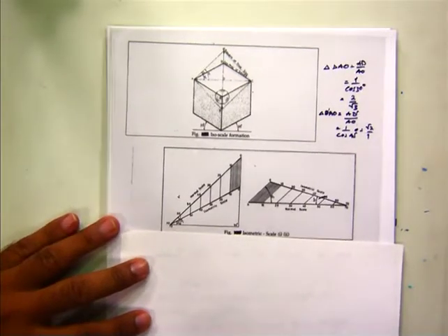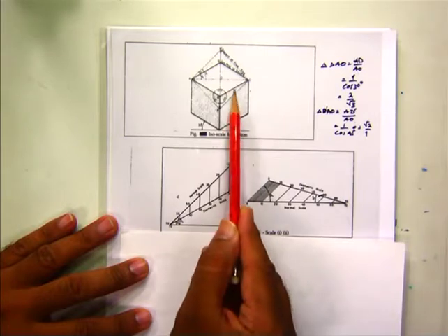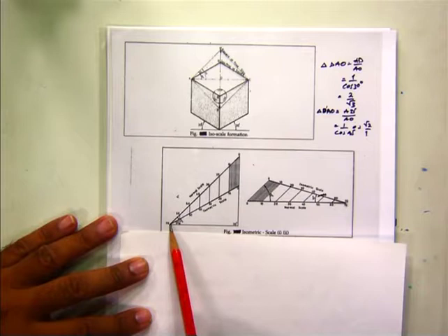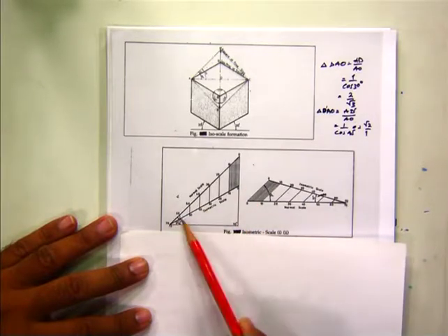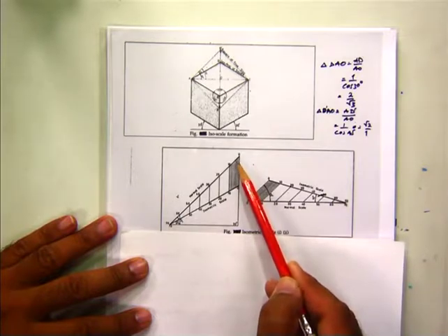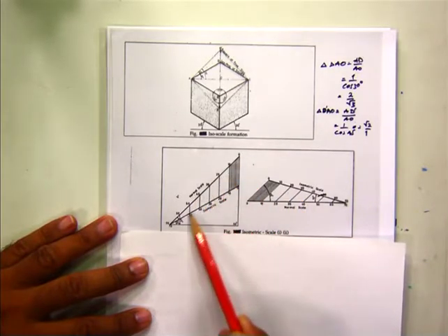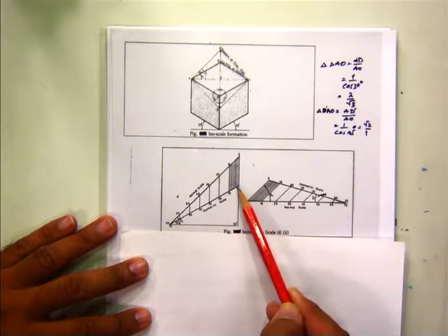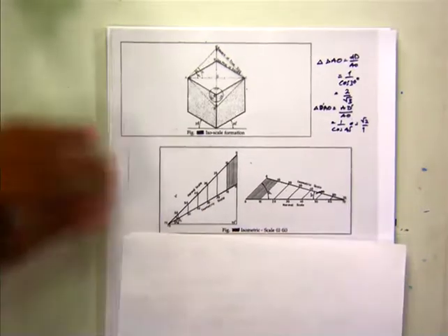We also studied what the isometric scale and the actual scale are, and how to form them. From here, when you draw the 30-degree line, it is the isometric scale line. From here, the 45-degree line gives the actual length. You take whatever dimensions are actual, and on this isometric line you will get isometric dimensions, which are reduced by approximately 9 by 11.